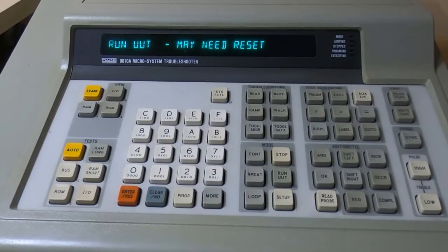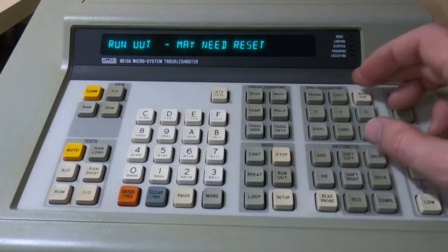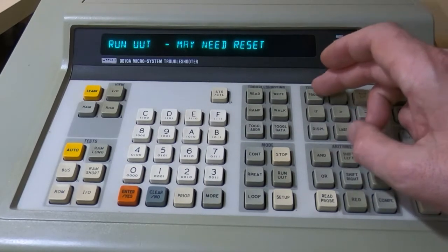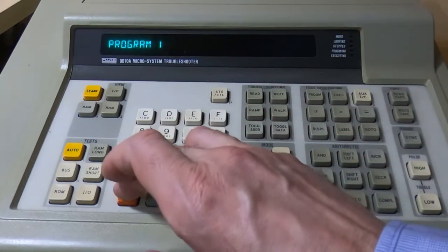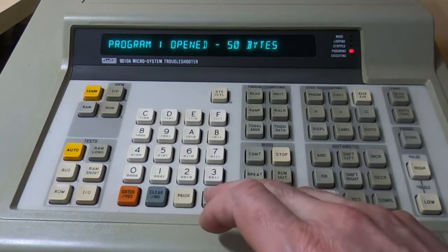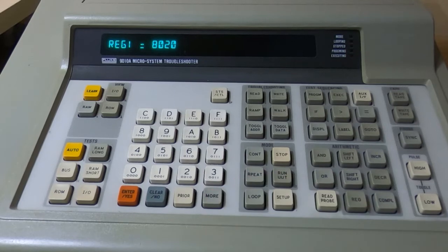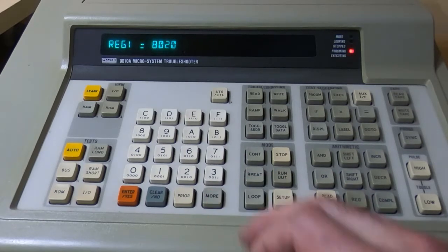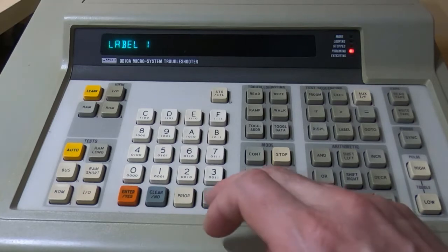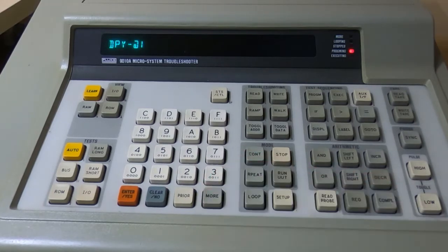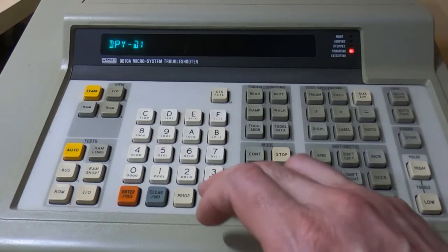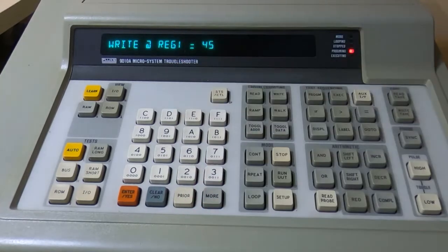Okay, so apologies again for any flicker on the display, but if we look at the two programs we've used so far, program 1 is the Fluke version of the program, and it works in a very simple way. We initialize a register with the address that we want to start writing values to on the target machine. We create a label so we can jump back to this point in the program. We display the value in register 1. And when I say display it, I mean we display it on the Fluke display, not on the unit under test. We then write the value 45 to the address that's currently indicated in register 1.